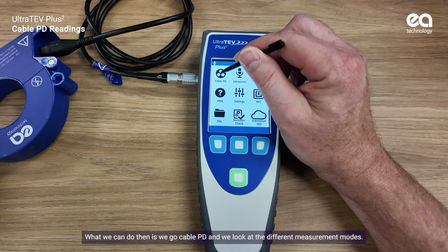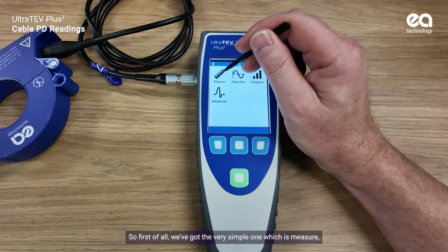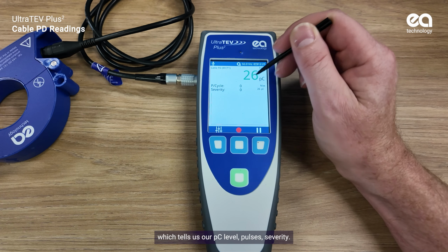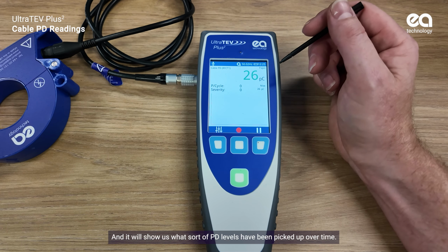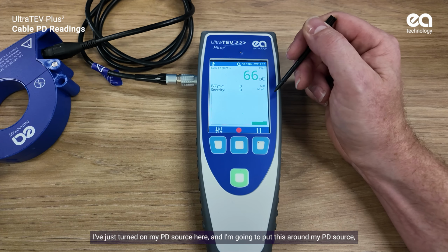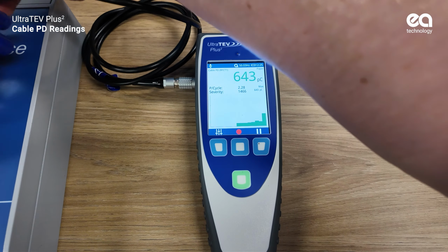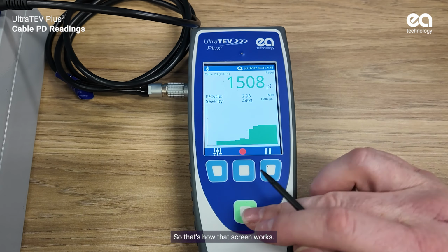What we can do then is we go cable PD and we look at the different measurement modes. So first of all, we've got the very simple one, which is measure, which tells us our picocoulomb level, pulses, severity, and it will show us what sort of PD levels have been picked up over time. I've just turned on my PD source here, and I'm going to put this around my PD source, which will pick up some signal for me. So that's how that screen works.